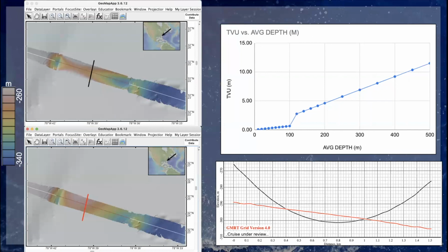The example you see here is in a transit swath file. We often encounter the most egregious sound speed errors in transit swath files. Here, the magnitude of the offset is nearly 40 meters in 300 meters of water. The IHO recommended total vertical uncertainty at this depth is roughly 7 meters.